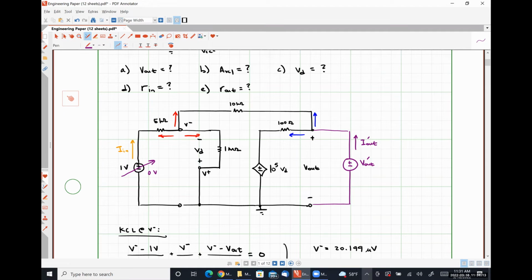The V out that we calculated at the beginning is the Thevenin voltage for this circuit. So we don't need to do that work again because it was already told to us. The only thing we need to do now is to reanalyze this circuit with the output terminals shorted to get I Norton, and that gives us an alternative way to calculate our output resistance lowercase r.